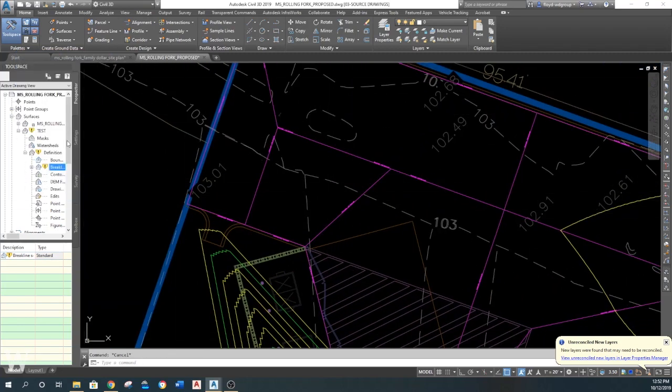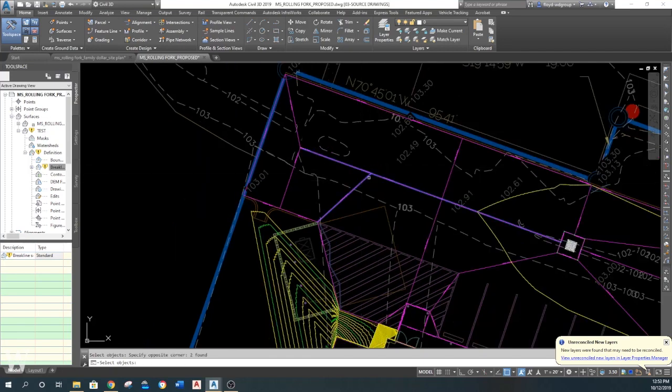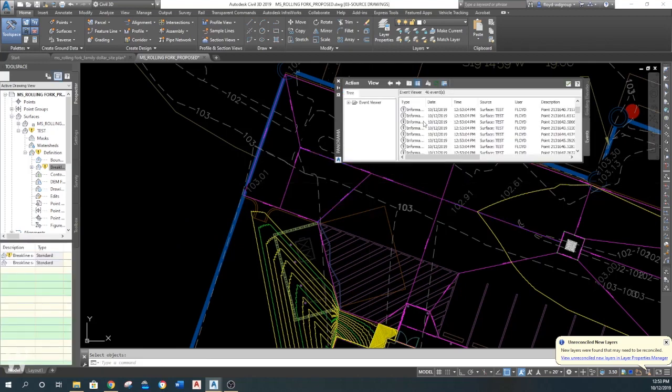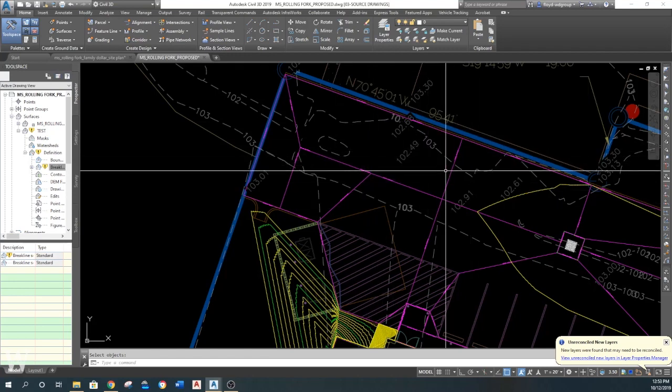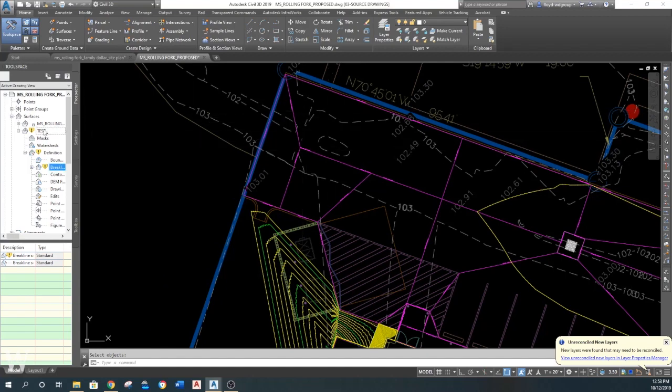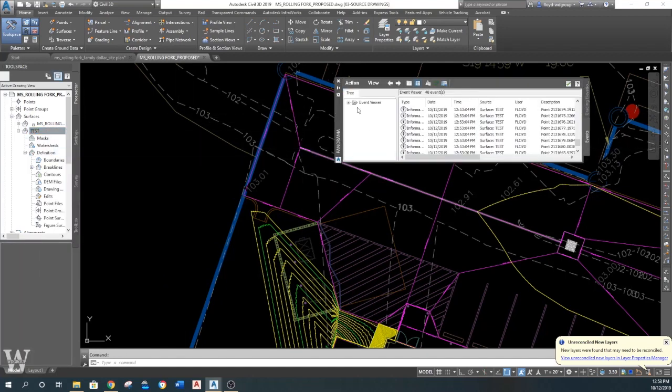So what we're going to do is we're going to go here. We're just going to take and add this break line that we just added. Now, sometimes I can't remember how many break lines I've added. So what you can do is we mess with all this, you can collect all those. It's going to give you some errors with that where you cross the break lines and some stuff. But as long as my surface looks fine, those really don't bother me on this kind of surface. And I'm going to hit rebuild.